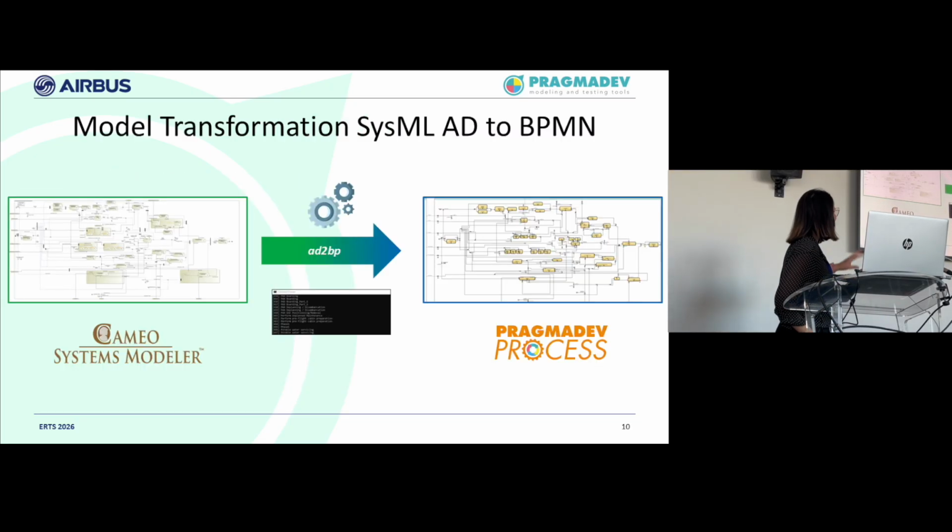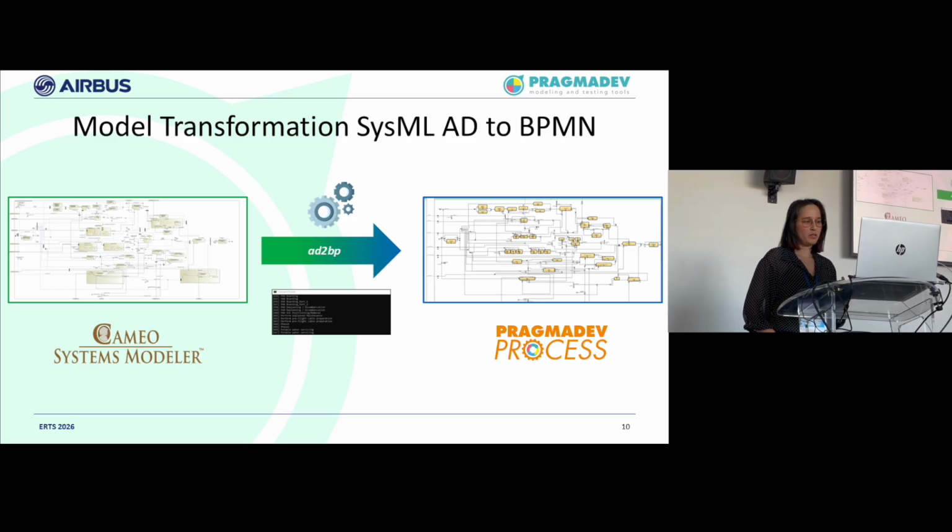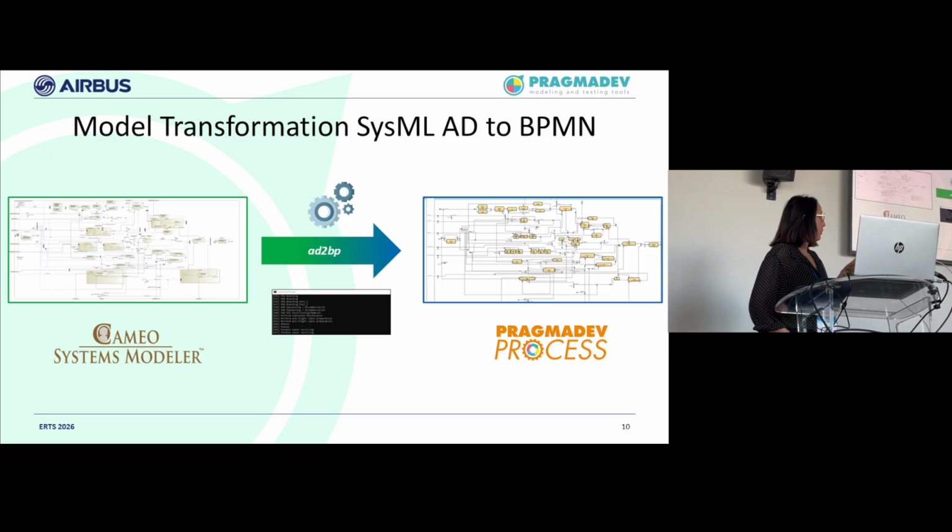So let's see how the model transformation was done. As I said, the SysML model or the operational scenario was done with an activity diagram. It was hosted in Cameo Systems Modeler. Thanks to the solution developed by Pragmadev, the AD2BP solution, we transformed the SysML to BPMN through an XML export. We retrieved the scenario in Pragmadev Process as a BPMN model, with no change to the content of the model, which is great, and this is what we were looking for.